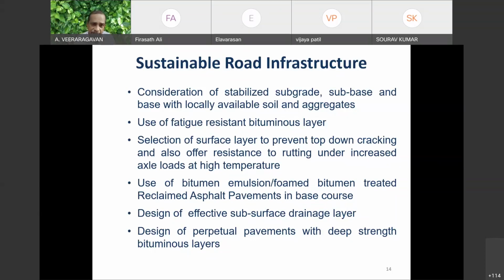Field issues are different. And I want a pavement, as I know, a pavement which is subjected to more and more traffic is subject to more and more repeated application, that is, subject to more fatigue. That means I need a material which can take repeated application of traffic load repetitions without cracking.